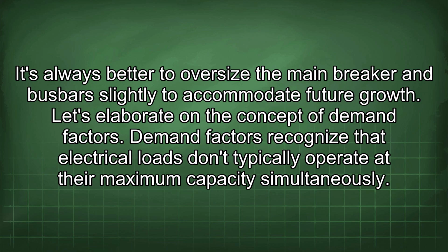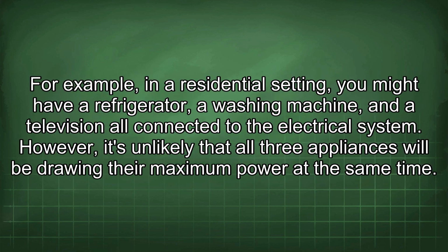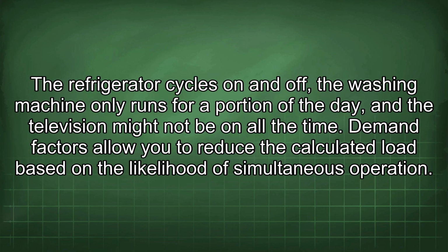Let's elaborate on the concept of demand factors. Demand factors recognize that electrical loads don't typically operate at their maximum capacity simultaneously. For example, in a residential setting, you might have a refrigerator, a washing machine, and a television all connected to the electrical system. However, it's unlikely that all three appliances will be drawing their maximum power at the same time. The refrigerator cycles on and off, the washing machine only runs for a portion of the day, and the television might not be on all the time.